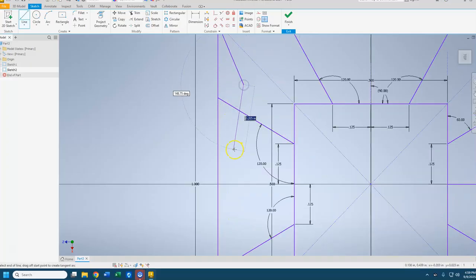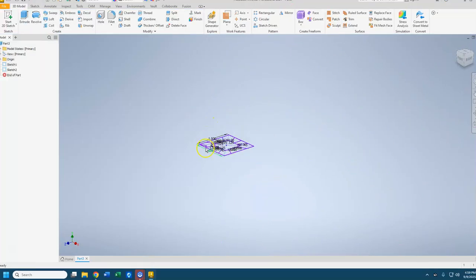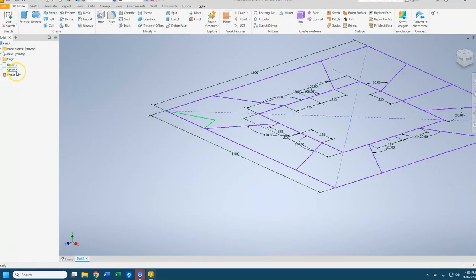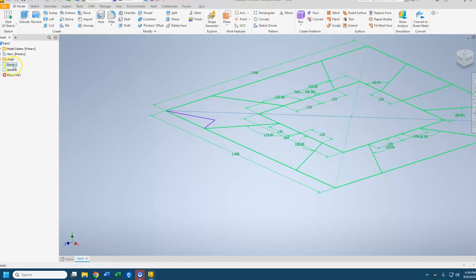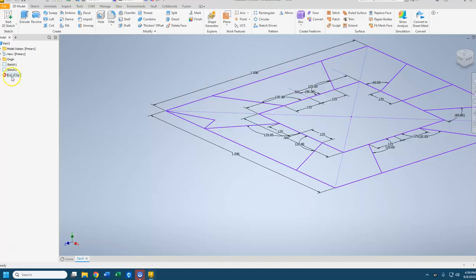What's happening is they're creating part of their drawing overlapping, but those are two separate layers. So if you look, I have sketch 2 and sketch 1. Those are on two different layers. Those do not interact. If I wanted to extrude this part, I'm not going to be able to. It's not a closed shape. So I'm going to right click and press delete.